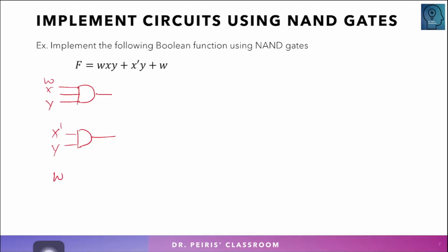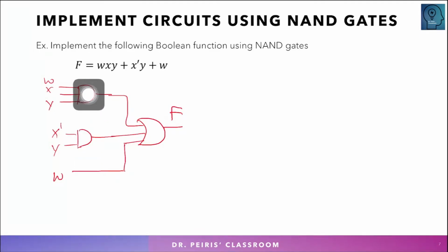To make the circuit symbol, you can just rewrite those input variables without drawing the wires everywhere. Now we have these three. They need to be combined through an OR gate. This is going to be a 3 input OR gate, and here is the output F. So we combine the 3 terms using the OR gate. Now we have drawn everything using AND and OR.